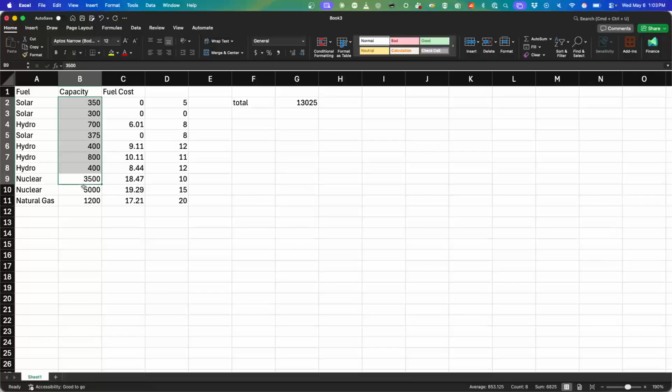So let's suppose that I only needed to satisfy 10,000 megawatts of capacity. The way that I would do it is, this is not quite in order, but it's almost in order. I'm going from lowest bid to highest bid. So I would do solar first, the row 3, because they bid at 0. And then row 2, bid at 5. I would turn both of those on.